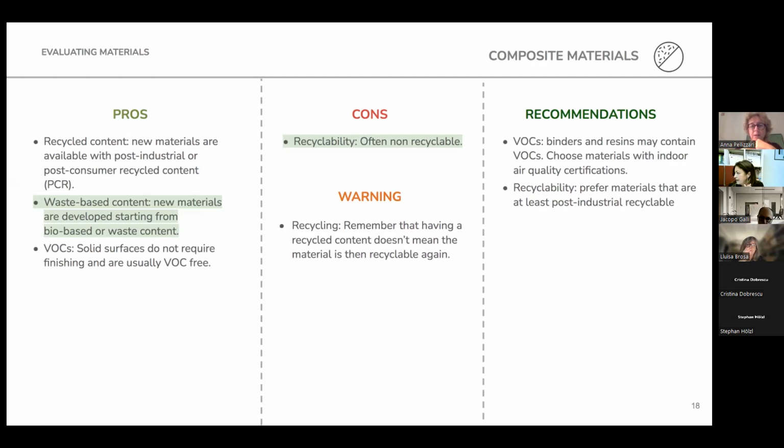There are some technologies to recycle composite materials, either standard composites, meaning for instance carbon fiber plus resin, but those are not very efficient, and they make sense economically only with very precious fibers like aramidic or carbon fibers, because the resin part would be burnt basically and used as energy recovery for the recycling, but you would lose the resin and you would just recover the fibers.